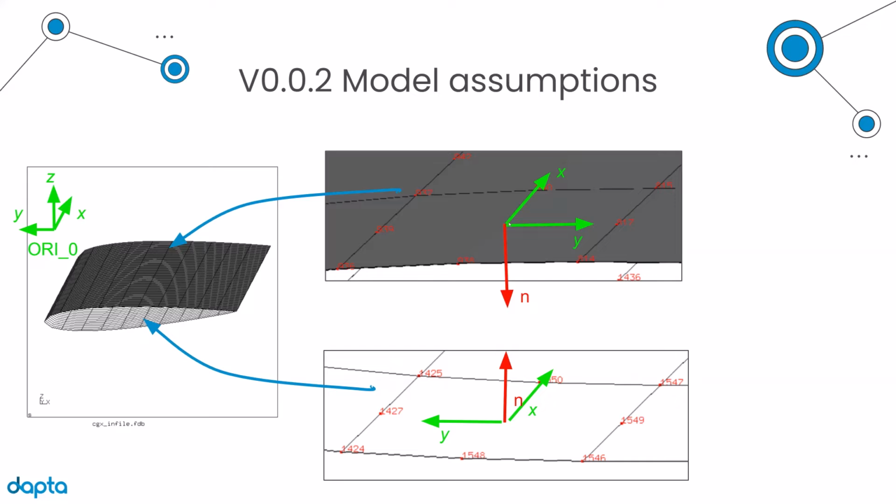And that means that when this orientation is projected onto our surfaces and respecting the shell normals, then we have a Y direction that is pointing aft on the top skin and forward on the bottom skin. And that's equivalent to actually having a continuous piece of composite ply that we're wrapping all the way around on our skin. And maybe that's what we want to model.